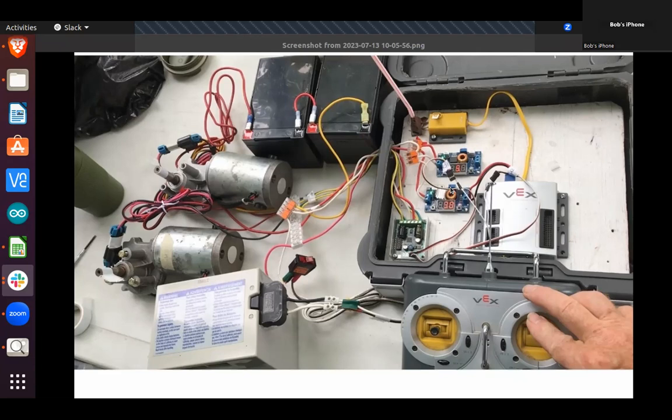I've read some cases where they've interfaced the Raspberry Pi into that silver box at the interrupts or at the analog and digital ports, but it's very, very limited. It's kind of binary stuff that you could do. So in theory, you could use a Raspberry Pi to control the VEX box with 1s and 0s, and then control the motors.